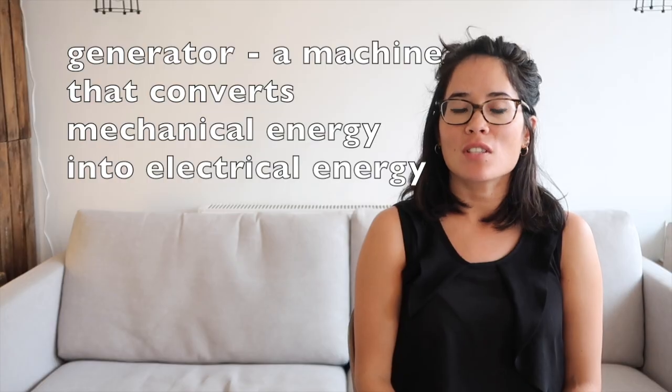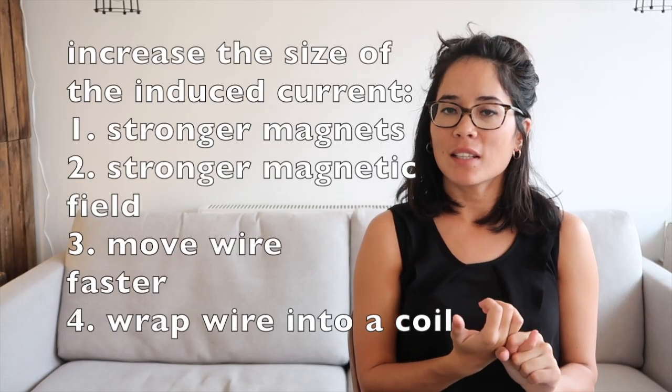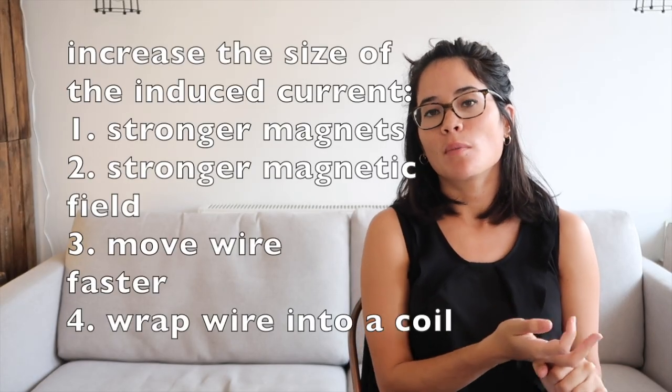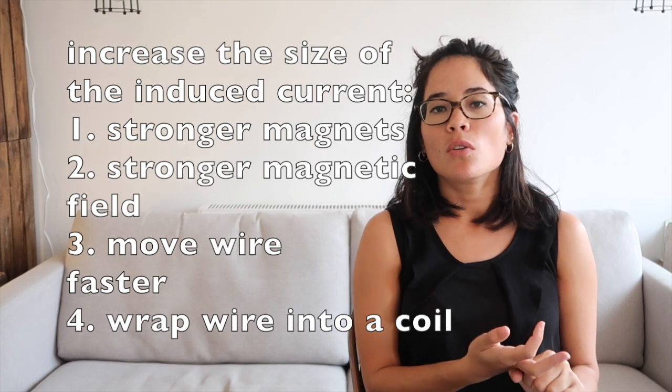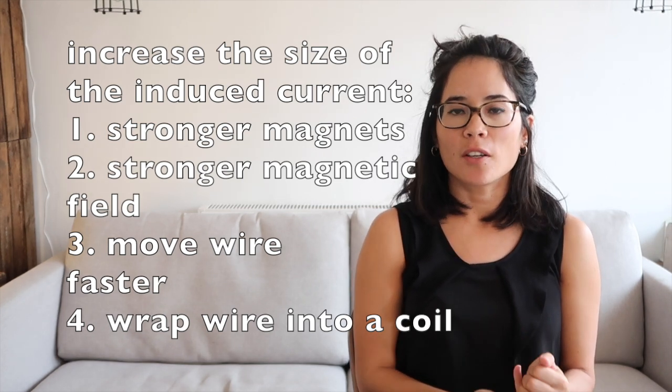And this is really how a simple generator works, because if you're creating current, then clearly you could make electricity from that, and all a generator is a machine which creates electricity. So how could you increase the size of that induced current? Well, clearly you could use stronger magnets, you could have a stronger magnetic field, you could move the wire more quickly, and you could wrap the wire into a coil.